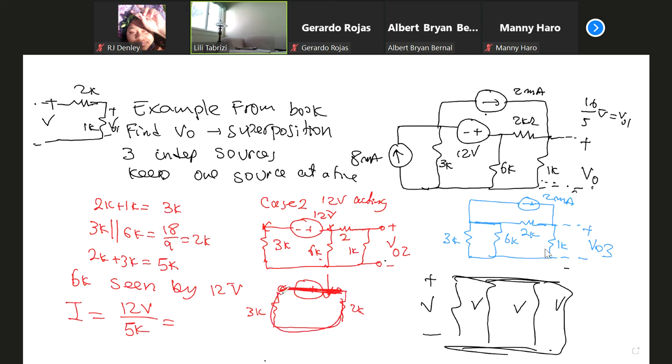Remember, finding equivalent resistance is terminal based. So if you're standing here, it's like moving it around, like orientation, plus, minus. What you have is 3K and 2K because you're looking into the circuit around this terminal. So you see 2K and 3K in series.